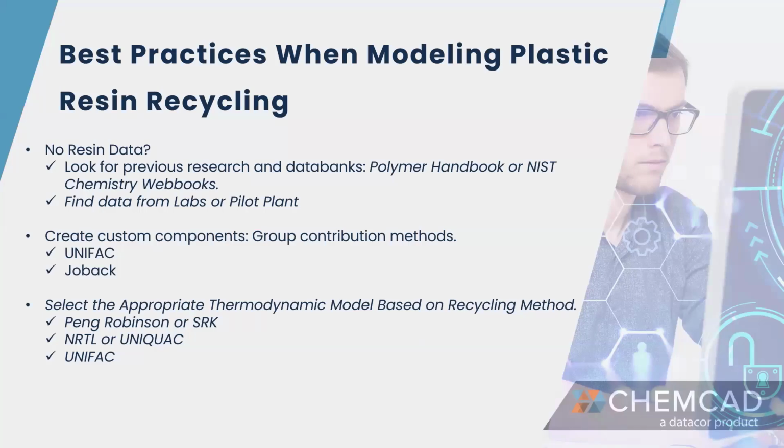So what are some of the best practices when modeling plastic resin recycling? A common challenge when modeling plastics in simulation software is that most simulators are built for traditional chemicals and hydrocarbons. So resins like PET or HDPE and PP often are not in their default databases.